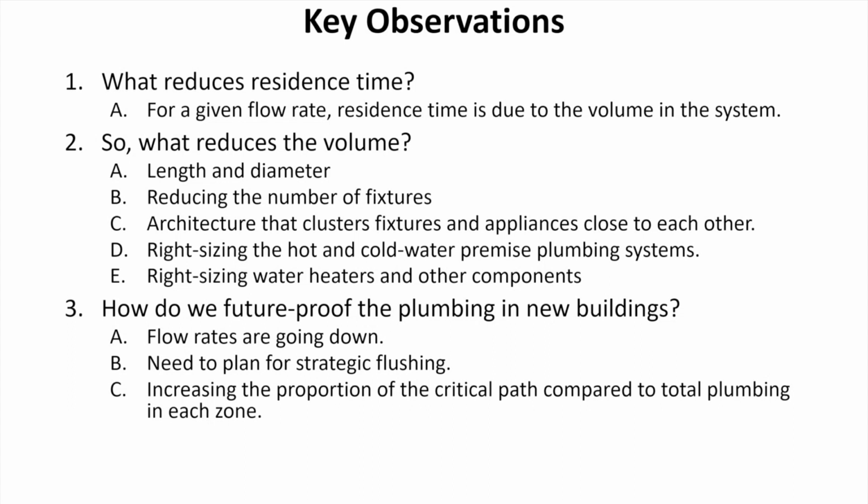The third part here is how do we future-proof the plumbing in new buildings? Flow rates are going down, at least as far as I can tell. I don't see them going back up. And so if that's true, we should be thinking really hard about the impact of the plumbing going into the building, because it's going to be there for the life of the building, pretty much. 50, 60, 80 years, even if we change it out. We rarely change out plumbing just because. We change it out when we're doing a major renovation or something failed.